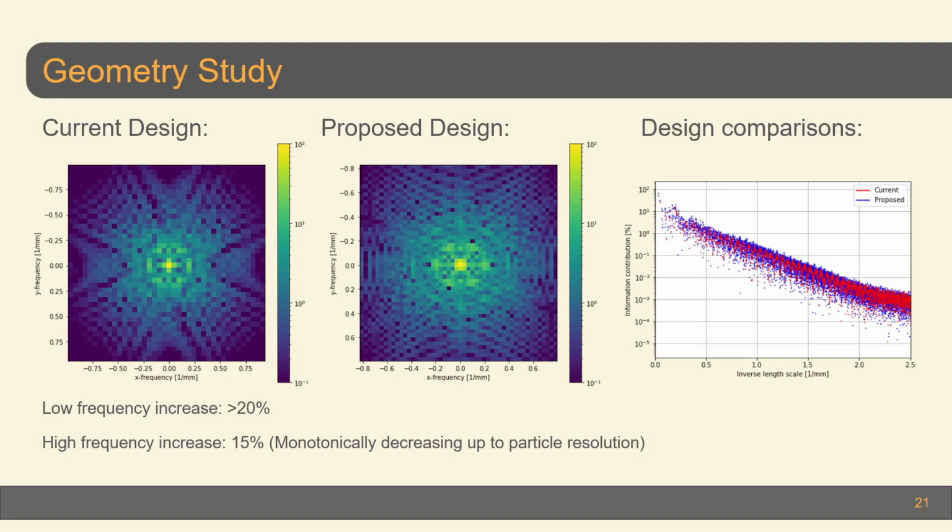You can of course see a qualitative difference between the 2D results already, specifically seeing the influence of eccentricity in the nozzle outlet. To really recover the quantifiable measure, however, we need to look at the 1D projection. In order to generate this projection, we combine the feature length scales in the x and y direction and recover an effective length scale. First of all, from a qualitative perspective again, we can see similar trend between the 1D results. Specifically, we can see that the cylindrical case has a very similar structure to the new proposed design.